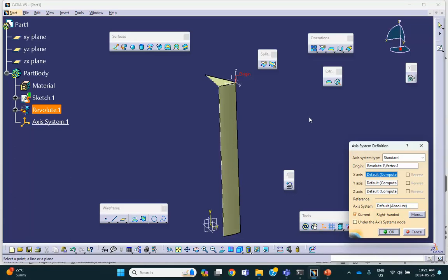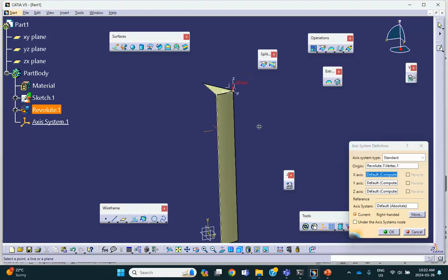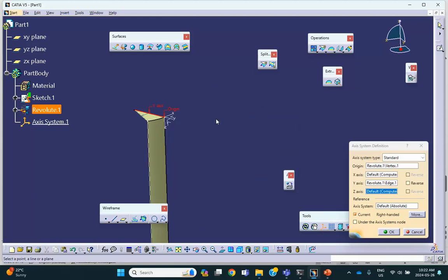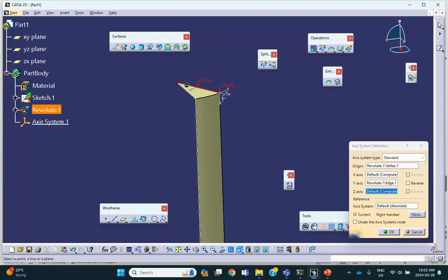And you can rotate this thing by 30 degrees, or the alternative is to say, for example, I want this Y to be aligned with that edge. That'll do the same thing. So I'm going to select the Y axis to be aligned with this edge. And notice that it did switch it so that Y is along that. And now, because of the way things are, this X is perpendicular to that edge.